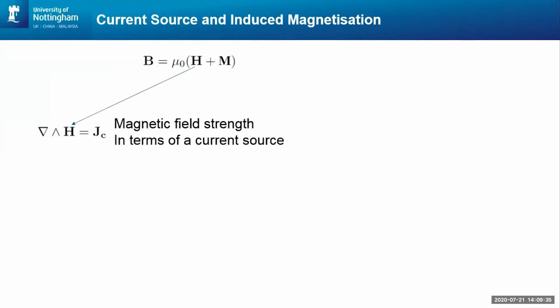So now we understand the boundary conditions, we've got to formulate the problem so that we can find an expression for the response of the magnetic field in terms of the initial current source. So to do that, the magnetic field is expressed by contributions of the initial current source H generated by a coil that's interior to the cylinder. But there's also the magnetization M, which is the magnetic field generated as an induced response to the initial current source.